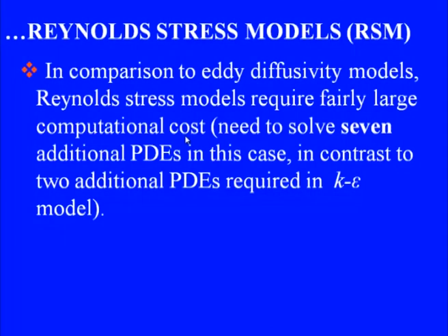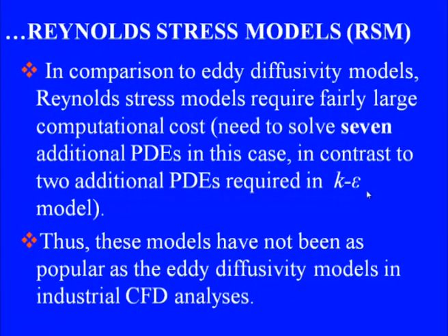So, that is why we would put a full stop to our discussions on Reynolds stress models, with just one observation that in comparison to the eddy diffusivity model, Reynolds stress models require fairly large computational cost. That is very obvious because we need to solve 7 additional PDEs, 6 for Reynolds stresses and 1 for the dissipation term, in contrast to 2 required in the k-epsilon model. So, it is pretty expensive, and that is one of the reasons why these models have not been as popular in industrial CFD analysis.